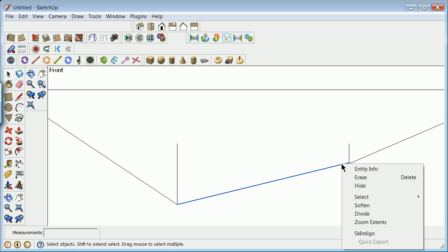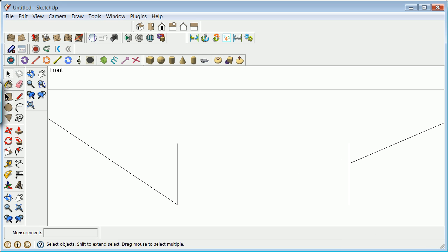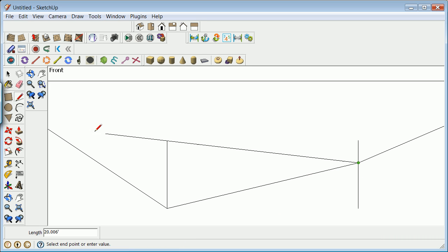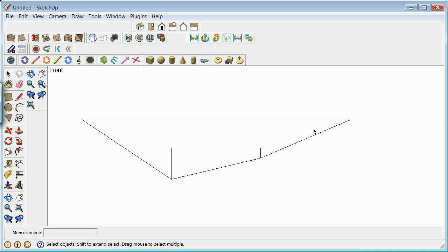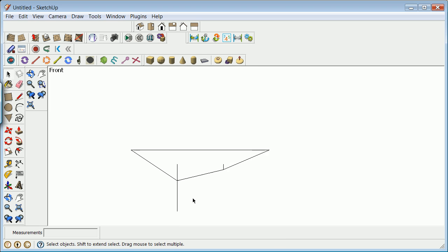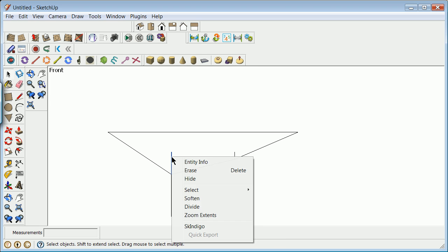You can't do the kind of grip editing in this program that you can in others, but there you have the general constraints of what we have here. And if you remember, anything to the right of this structure is unknown. We had a force going down from here. I'm going to put it down at 10. That was what was causing that structure to deform. We don't need this anymore.